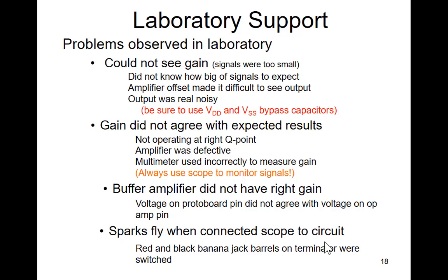The red banana jacks. Every once in a while you've got somebody that does a real nasty thing. We have those banana jacks in the laboratory. Has anybody ever gone in the laboratory and had the red and the black turned around? Normally black is ground, and red is positive. Have you ever been in there when the black is on the positive side and the red's on the other side? I've been in there many times when that's happened. Somebody has screwed around with them, and so now you're putting 10 volts across ground or something, and you get a spark.